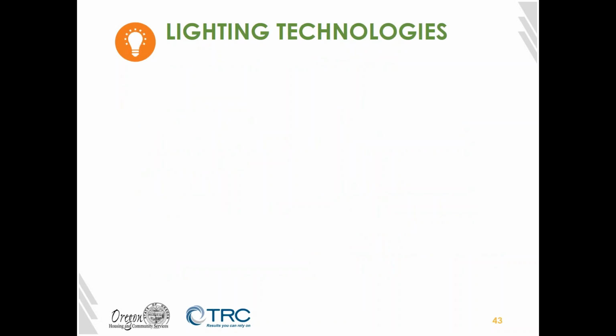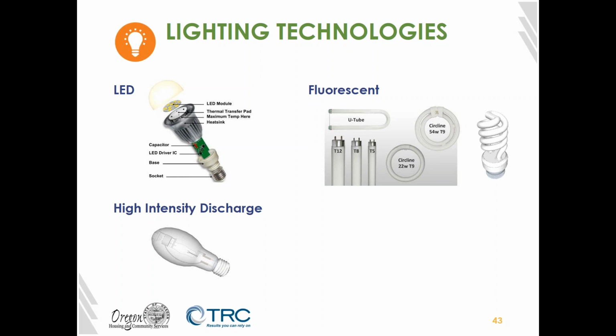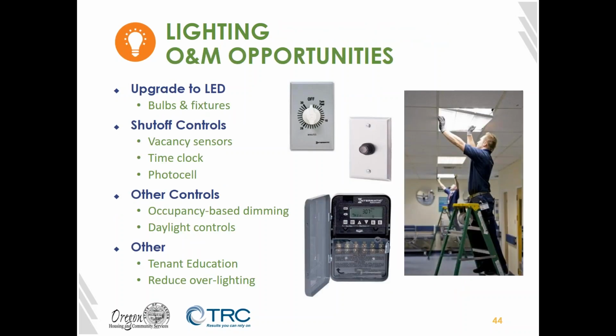For lighting, in terms of lighting technologies, these days most things folks are installing are based on LEDs. We might still have some high intensity discharge lamps out there, like high pressure sodium or others. There are also plenty of fluorescent lights out in the world, linear or compact fluorescents. And then occasionally you might come across an incandescent bulb or two. These are going by the wayside, and kids being born today will grow up in a world that is mostly devoid of incandescent light bulbs, and that might make some of us sad, but it's ultimately good for the planet.